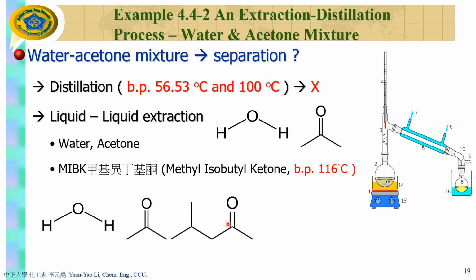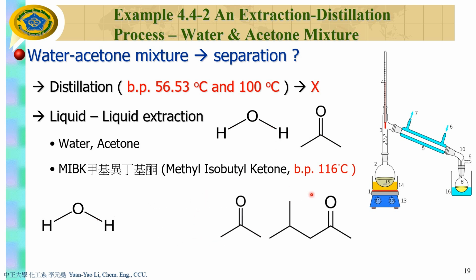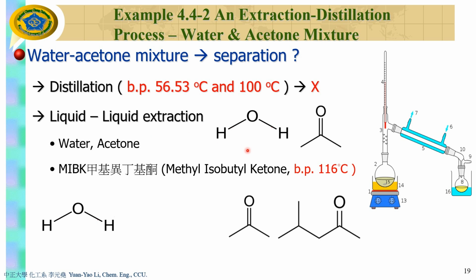So MIBK can dissolve acetone, but cannot be dissolved in water. If you put the MIBK into this mixture, the MIBK will take out the acetone. So you can do the separation of water and acetone by liquid-liquid extraction. Again, I introduced MIBK into this mixture, and the acetone dissolves into the MIBK.